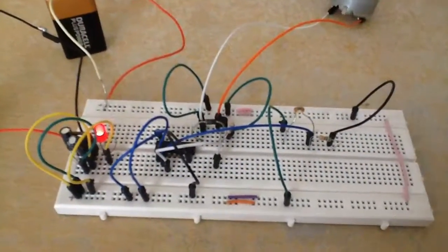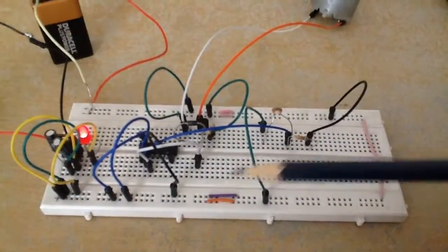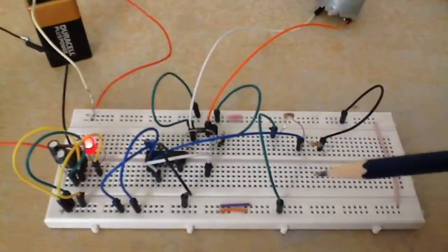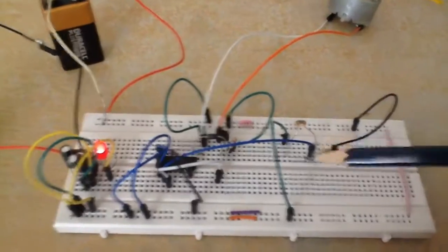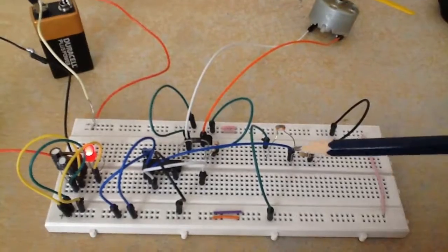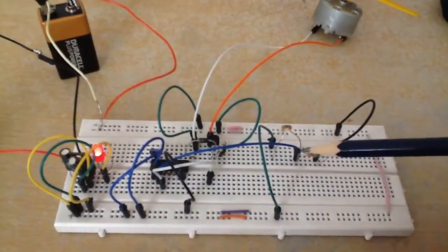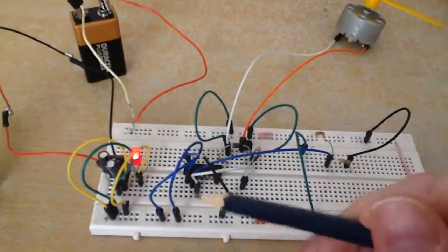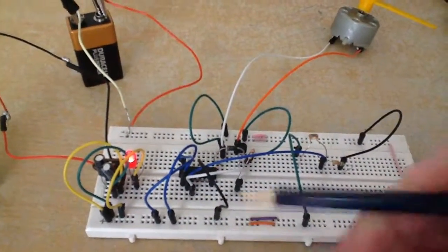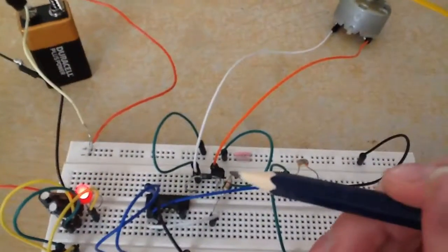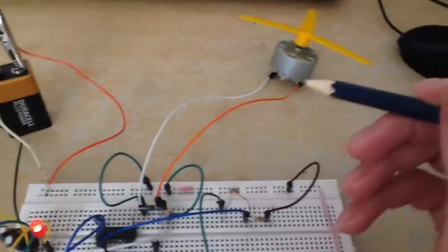In this next circuit, we've removed the LED, and now I want to turn on this motor with this fan on top of it. The same principle applies as before. If I put my finger over the LDR, this will ensure that we get around 0.8 volts at the output, which is enough to ensure that pin 2 goes low. Then pin 3 will go high, and that will turn on this transistor, which is used to drive this motor.